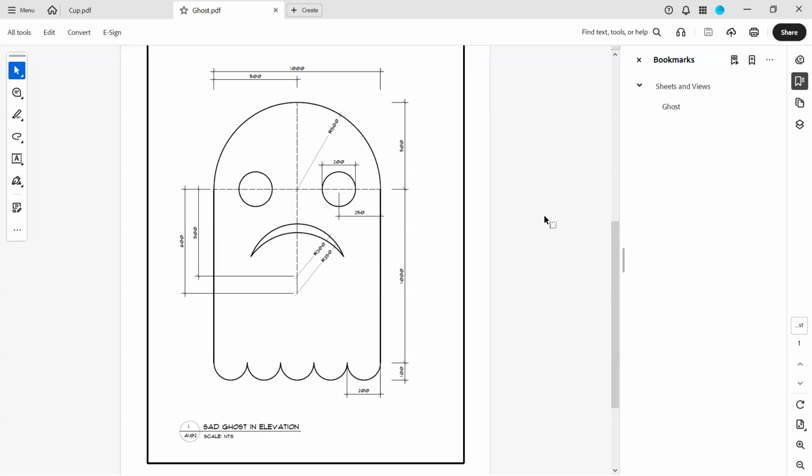Let's say offset, enter, then 500, enter, select that line, and then yeah, there, that's the 500. Click anywhere. So that's 500. So from there, you can draw a circle. The radius is 300.